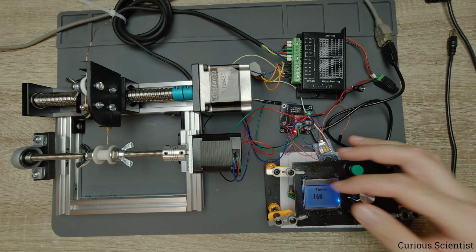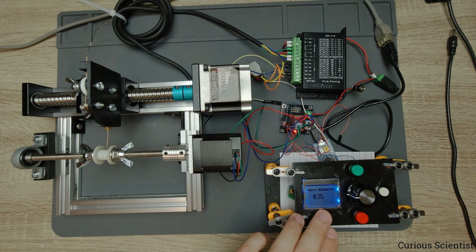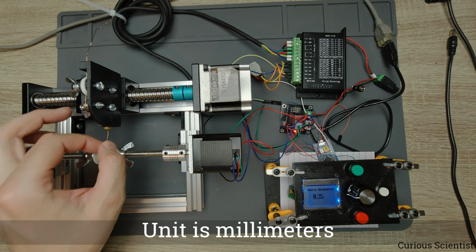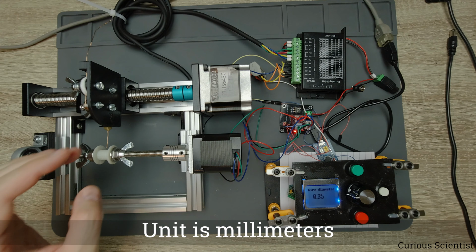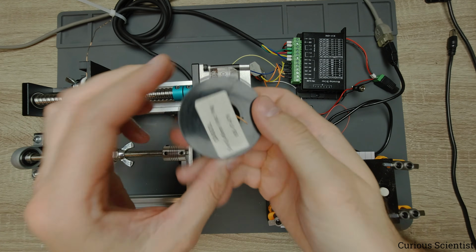And then we have the number of turns which we can feed. So that will be the number of turns on the bobbin. And then we have the wire diameter, but you have to be careful about it because sometimes they provide the wrong value on the bobbin, like here.